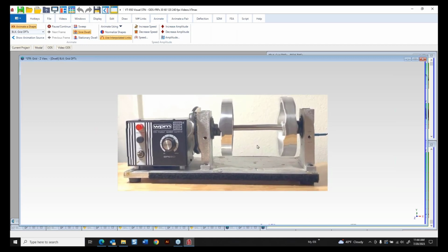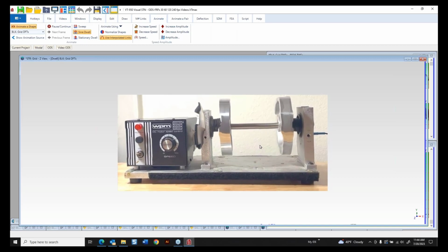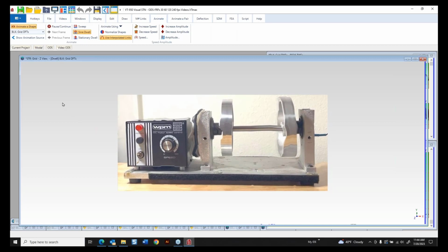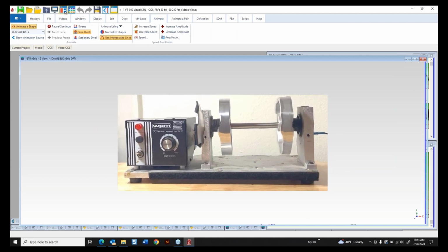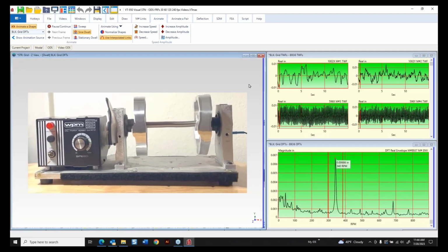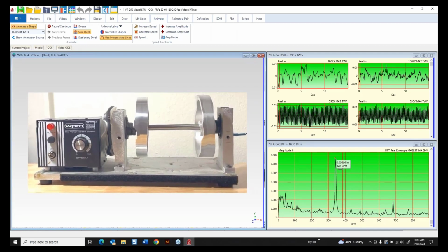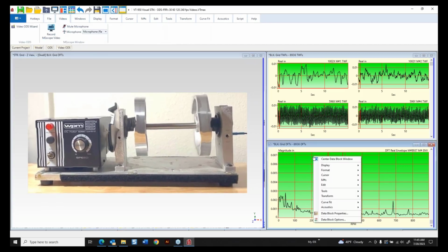And that's true. I've done experiments on other rotor kits where you can see the mode shapes as you go up in the orders. You can see all the mode shapes dominating or contributing to each order. Okay, what else to say? Let me put this back over here. Again, if I go down here and look, this came out just really nice. I can integrate this data.